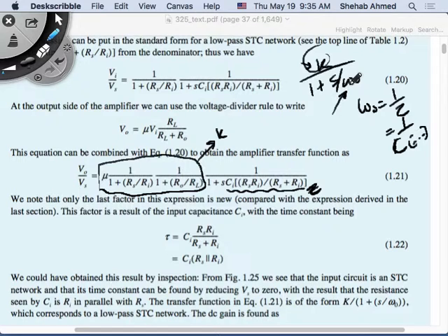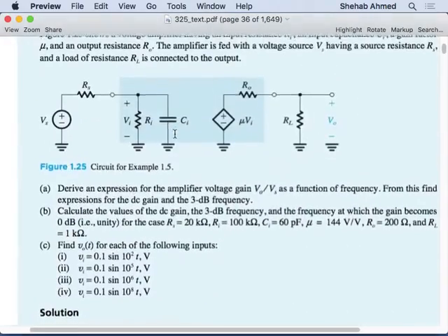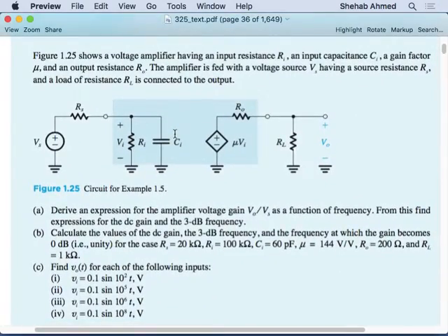So one smart way to find omega naught is to look at your circuit and just find tau. How do you find tau? You have a capacitor. A good, easy way to do this is to look at the terminals of the capacitor, short any sources, and look at what resistors are in parallel with the capacitor, and that will be your circuit time constant.